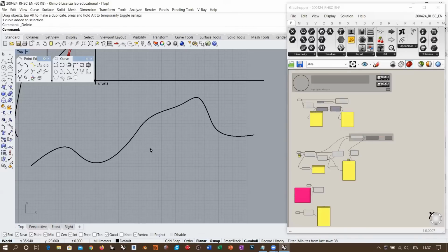So let's go back. This continuity here in Rhino is called position continuity, and it's called so because the position of the endpoint of one body corresponds to the position of the start point of the second body. So it's just a contact continuity, position continuity, and it is schematically named G0. Let's say the nickname of position continuity is G0. So we have G0 continuity here.